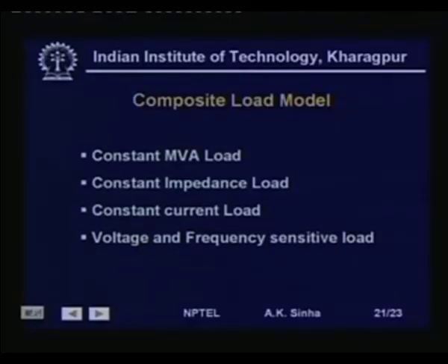For most of the system analysis that we do, especially the steady state analysis, that is the load flow analysis that we carry out for power systems, we have to model these loads either as constant power loads, that is, P and Q remain constant at that point, or as constant MVA load.